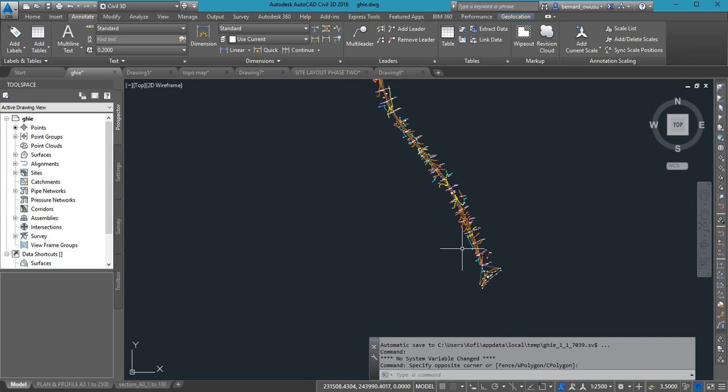Okay, then after the walkway, we may have a drain, it may not run through, but let's say a drain of width 1 meter. So for both sides, we have 1 plus 1. That is 14.3. So it means that at worst, if we are even to go through town, the minimum width that we should have should be about 14.3 meters. That is about 7.15 for each side. So please take note of that value.